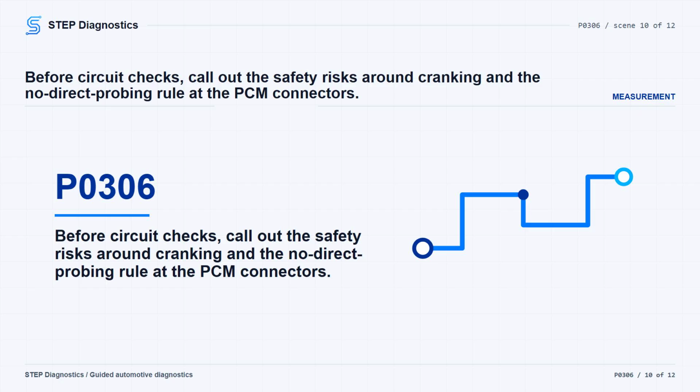Turn the ignition on, actuate the ASD relay with the scan tool, and use a 12-volt test light connected to ground to probe the ASD relay, F342, output circuit at the coil connector. If the light does not illuminate brightly, stop scan tool actuations and repair the open or short to ground between the PDC and the ignition coil connector, then verify.